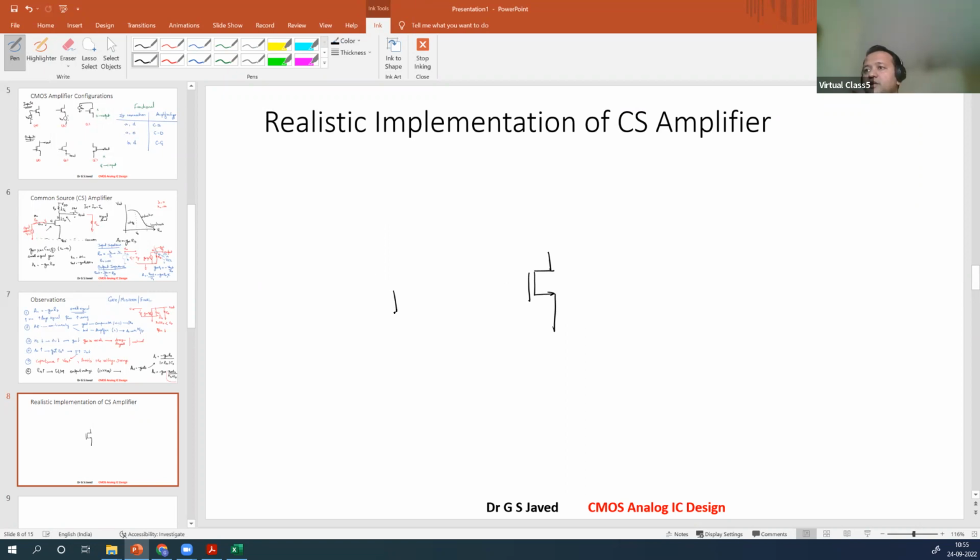With this, you would now like to apply the bias condition. Now you will have a DC bias coming, or an AC signal, Vsignal. You have the source signal resistor here. Now you do not want any DC signal to get transferred, which will impact your bias condition. So you block DC with a blocking capacitor. After you block the DC, you need to bias it at your DC operating point.